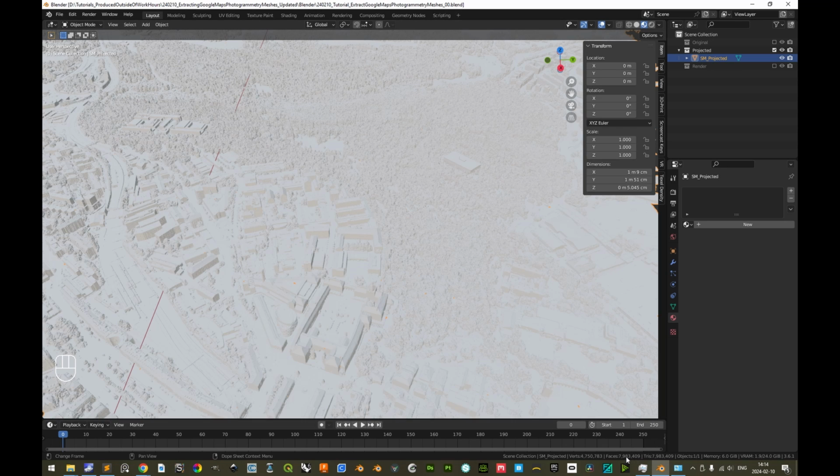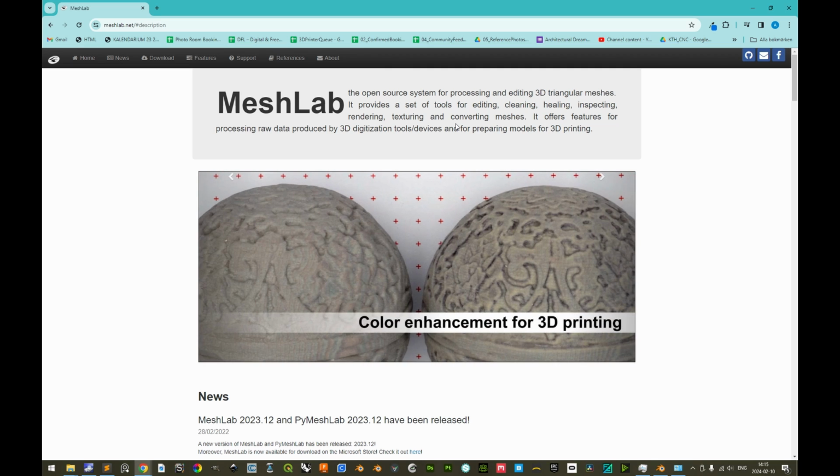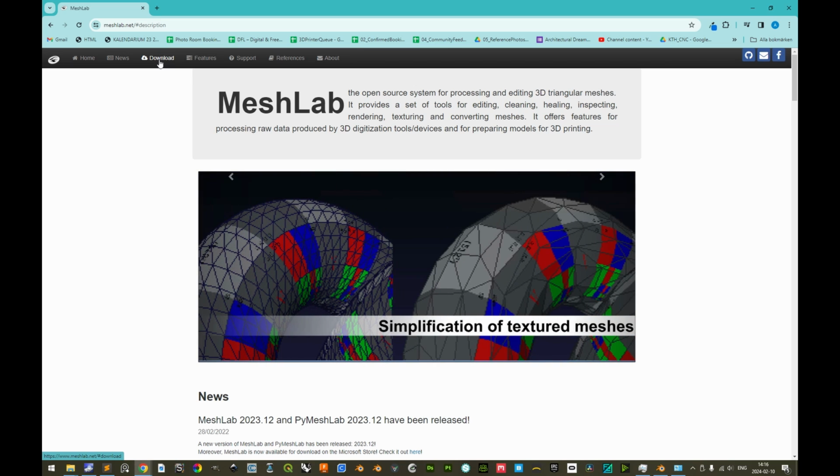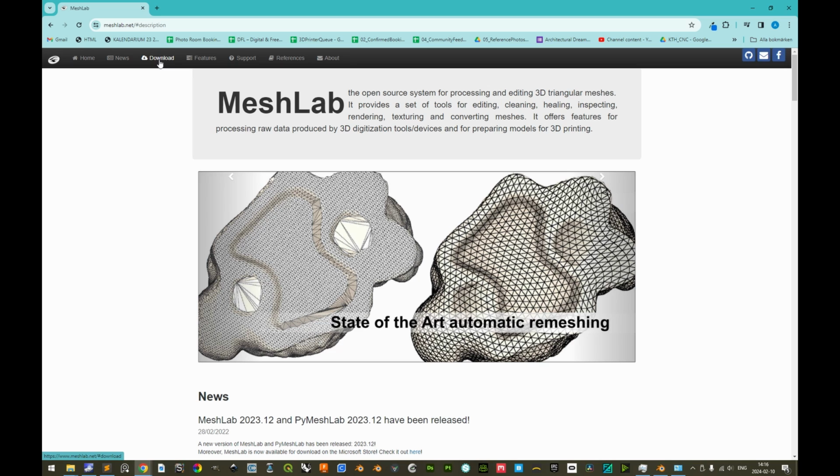Since this object has almost 8 million triangles, it is going to be very, very cumbersome to do this in Blender. Even though Blender has excellent UV unwrapping functionalities, it will be too time consuming to use it within Blender. So what is recommended at this stage is, if you do not have it installed, to also install MeshLab. It's an open source mesh editing software, and it has a nifty feature where you can unwrap an object into individual faces, which will be very time efficient and also totally adequate for our referential purposes for this mesh.